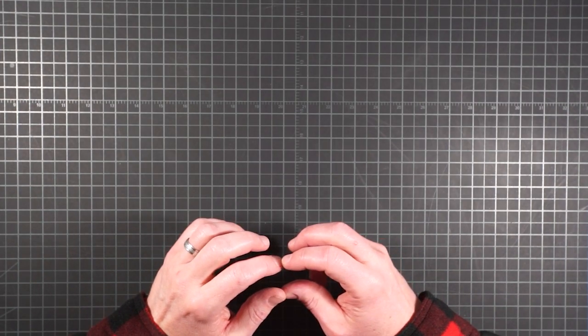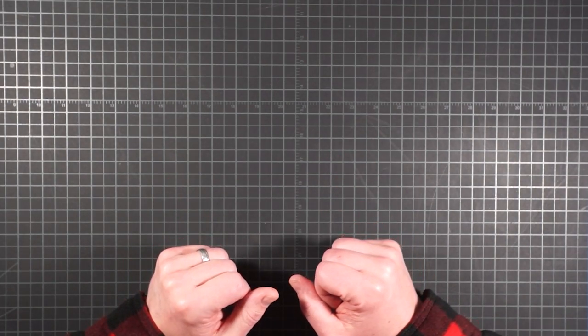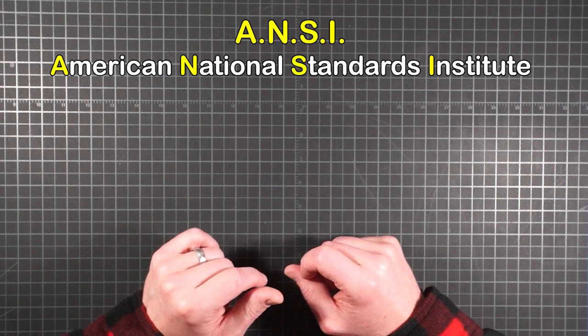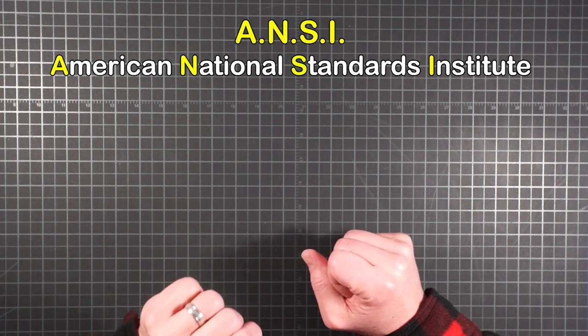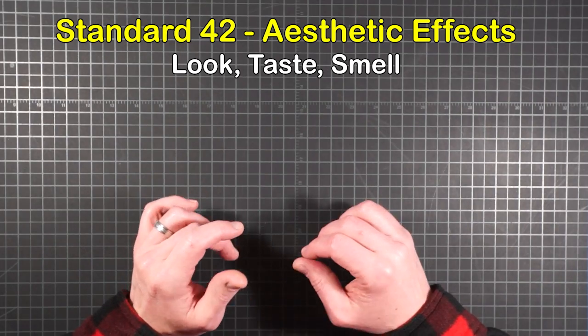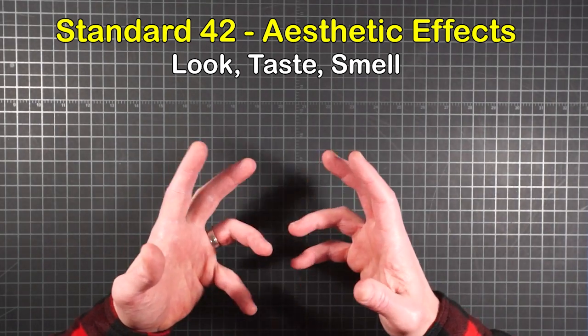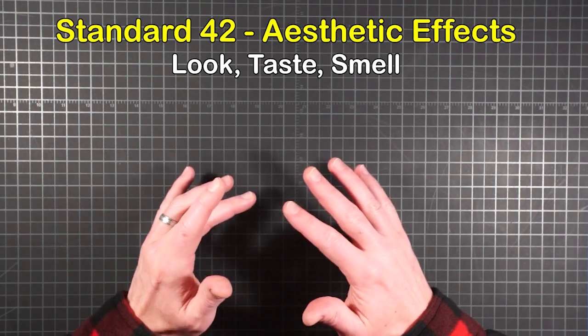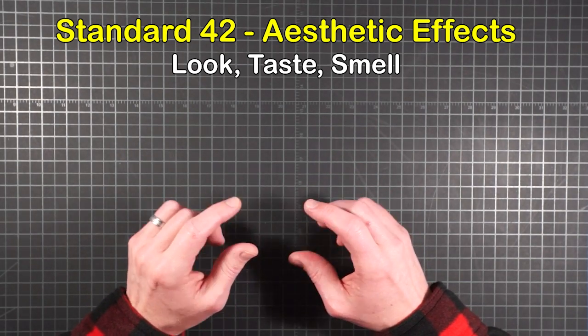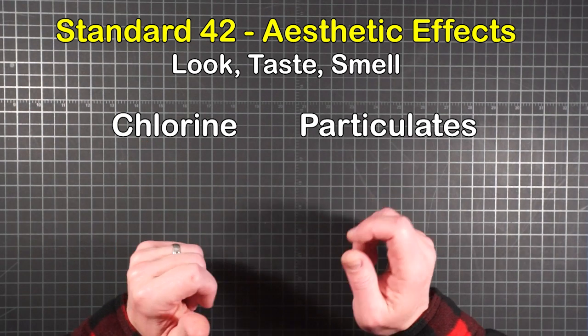So how do you know exactly how much of what was removed? Well, ANSI, the American National Standards Institute, works with the NSF to create standards for water filter performance. And Standard 42 is set for aesthetic effects. It's for things that might spoil the look, taste, and smell of your water, but aren't considered a particular health hazard. And there are two main types of contaminant removal rated under this standard, chlorine and particulates.